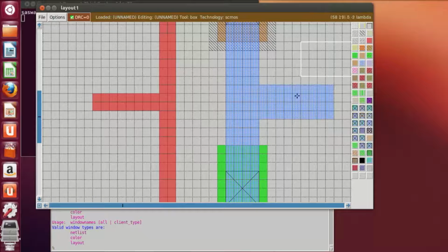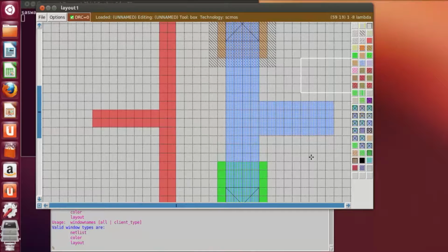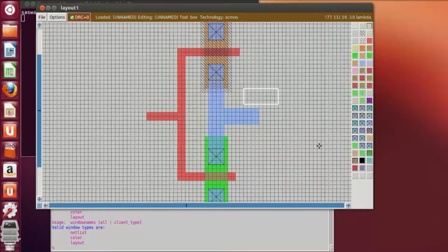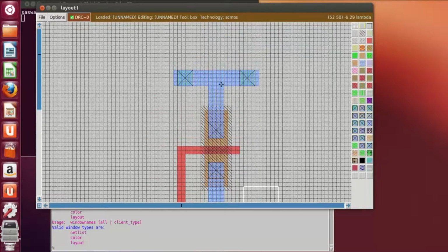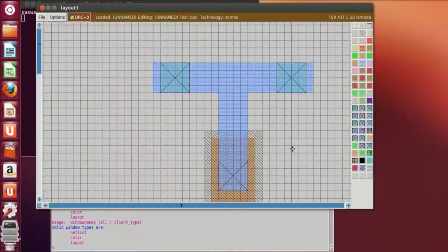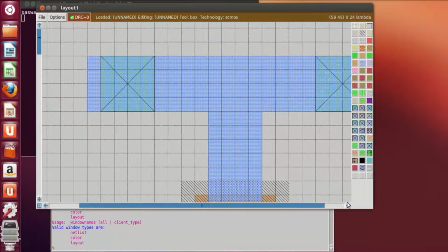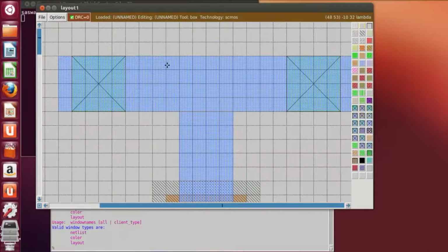Middle click on metal. Now this is the input, gate terminal is the input and the drain terminal is the output. This is not a compulsory rule, but over here the input is taken from the gate. So before that, zoom in, we have to label the VDD.